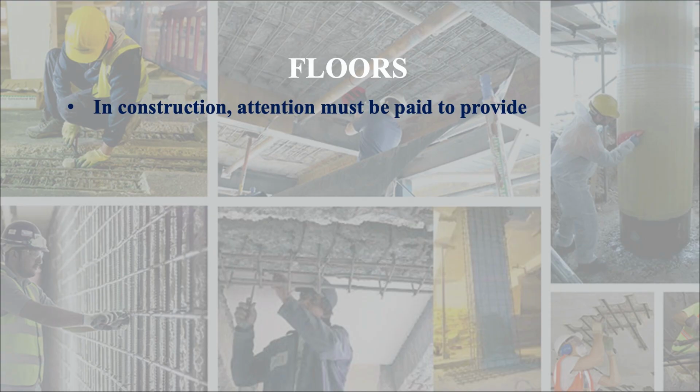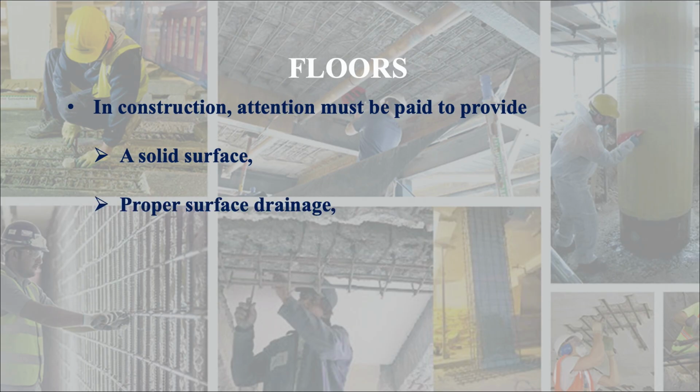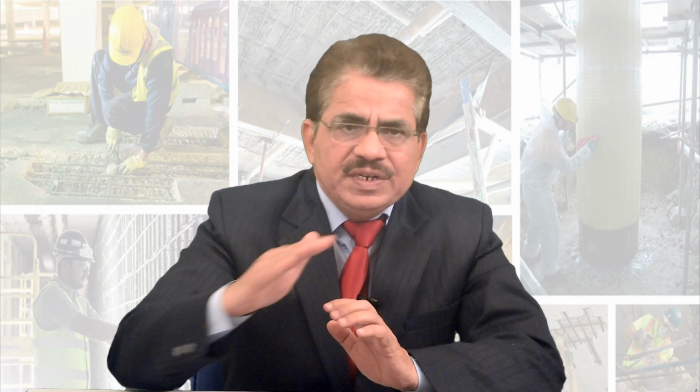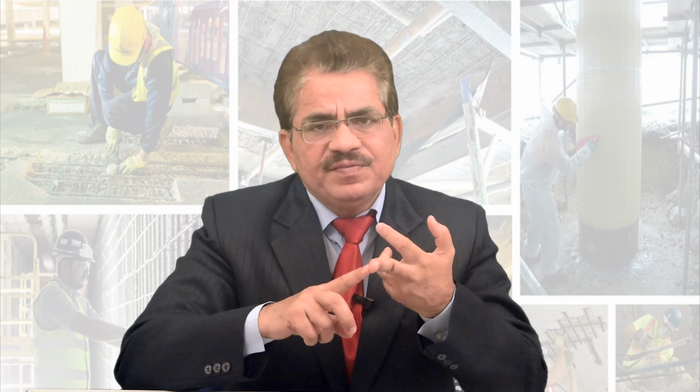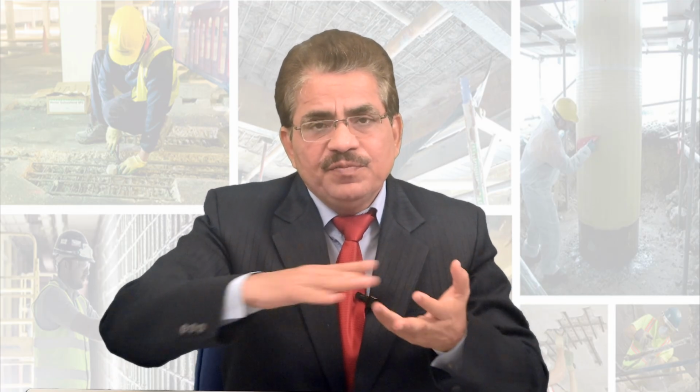In construction, attention must be paid to provide a solid surface, proper surface drainage, and also appropriate joints. So three things are important here. First is a solid surface. Second is proper surface drainage, because if proper slope is not there in the floor, then there will be stagnation of water and certainly it will cause some defect.